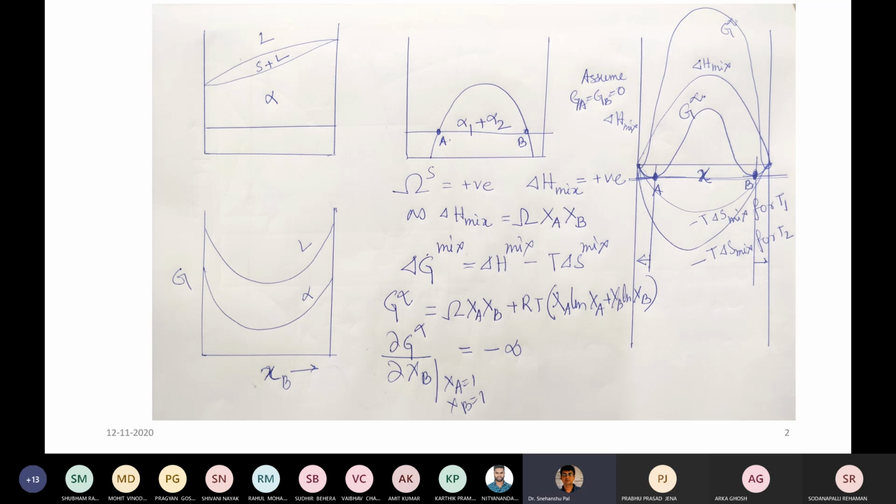So this is alpha 1 and alpha 2, and you do not call them alpha or beta basically because both are the same structure. It is actually one single phase which is decomposing into two with the structure remaining the same, except the compositions are different. So as a result, the whole thing is alpha splitting into two, one having the A rich composition, another having the B rich composition. Forget about spinodal, I will discuss that later.